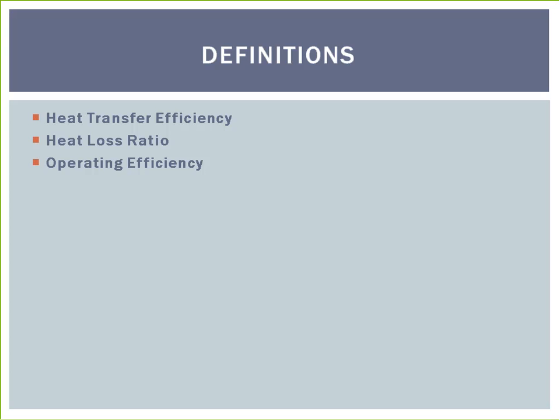Operating efficiency, also called seasonal efficiency, of the boiler relates to the actual and ever-changing conditions found within a facility, how the boiler reacts to the load, and the amount of fuel consumed over a period of time. This value is not generally quantified by a boiler manufacturer due to the many variables involved in daily operation, and variables due to the building envelope itself.